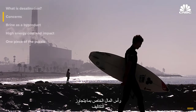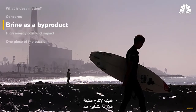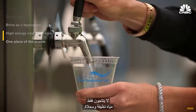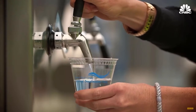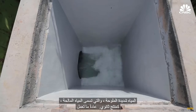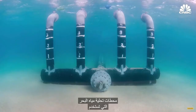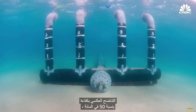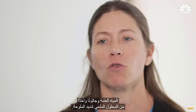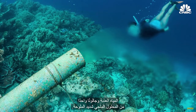Beyond the environmental costs of producing the energy needed to power these plants, another concern arises because they're not just outputting clean, desalinated water. They're also producing huge amounts of hyper-salty water called brine as a byproduct. Seawater desalination plants that use reverse osmosis typically operate at a 50% efficiency in that if you take in 2 gallons of seawater, you're going to produce 1 gallon of fresh water and 1 gallon of hypersaline brine.